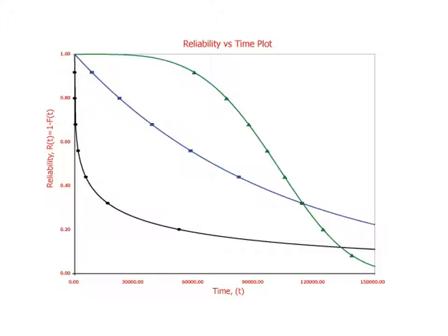And so each of these has a different underlying probability density function. The one we saw just a minute ago was this sort of normal Gaussian-looking distribution. But if the shape of that underlying density function changes, then the corresponding reliability function changes. So the reliability function here we're measuring directly as 1 minus the cumulative distribution function.